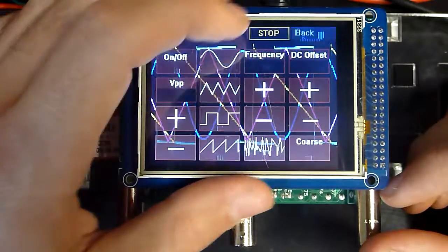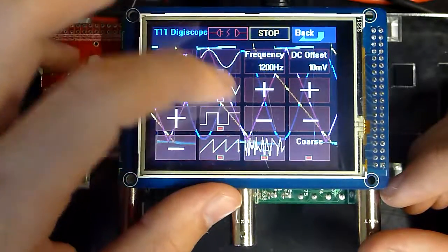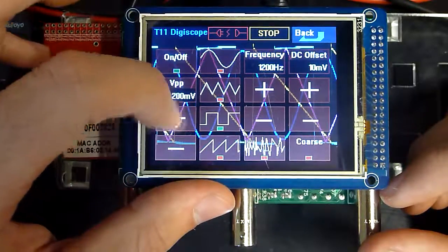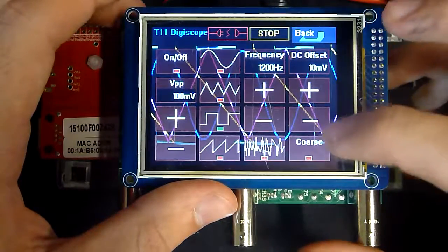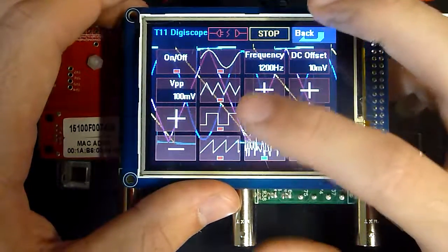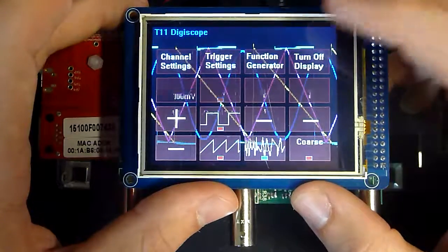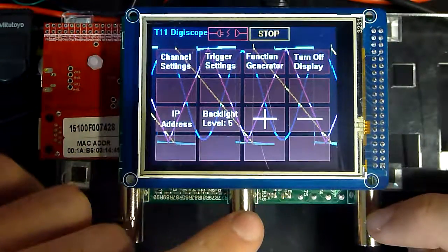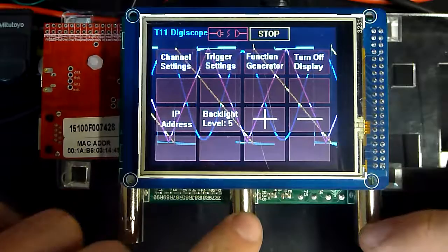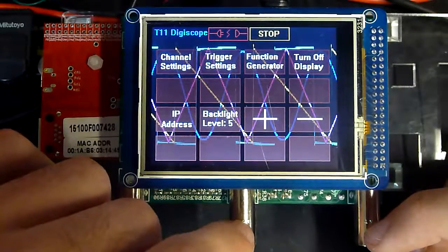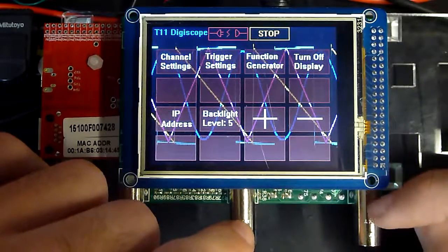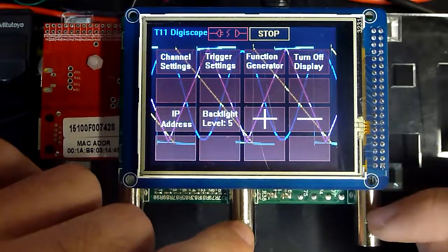The function generator can go up to 25 kHz, and you can select the various waveforms here, control the amplitude, DC offset, go for random noise, whatever you want. And then on the input channels, we had one mode where it was low pass, so we had to take in a signal from 0 to 250 kHz, and then there was a bandpass mode from 650 to 750 kHz.